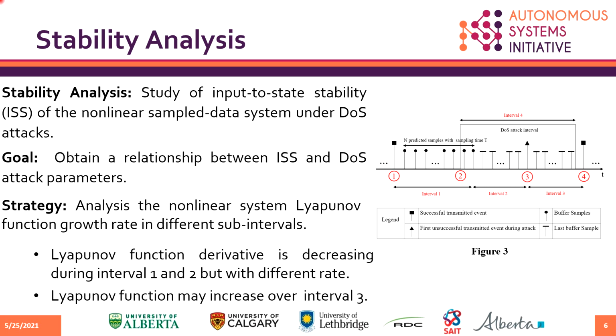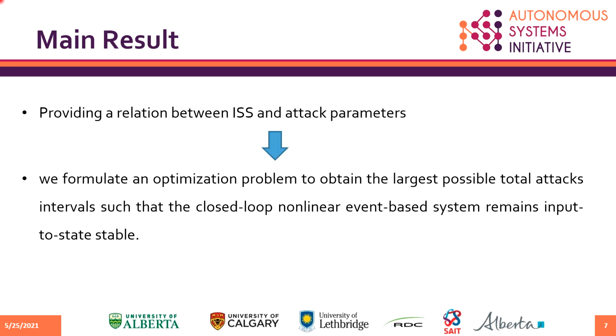Finally, we can find an exponential upper bound for the Lyapunov function valid for all time, and input-to-state stability is obtained if the exponential function has a negative rate. Our main result is providing a relation between input-to-state stability and attack parameters. In other words, we formulate an optimization problem to obtain the largest possible total attack intervals such that the closed-loop nonlinear event-based system remains input-to-state stable.